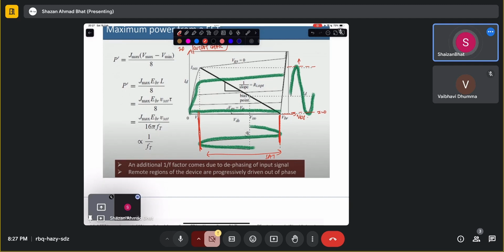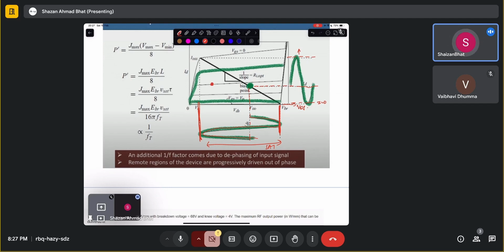So that's why you create something called a bias point. You want them to be exactly in the middle, ideally. You want them to oscillate around this value only, because if the point is around here and it swings around here, it will be huge on this side, and on the bottom side this part will get clipped, because it's in the linear region.